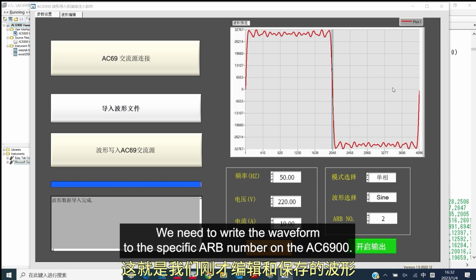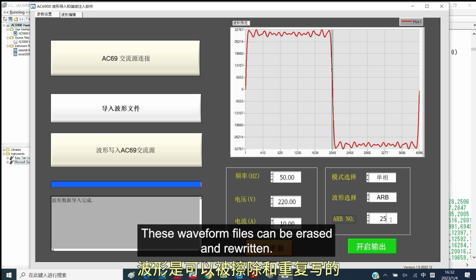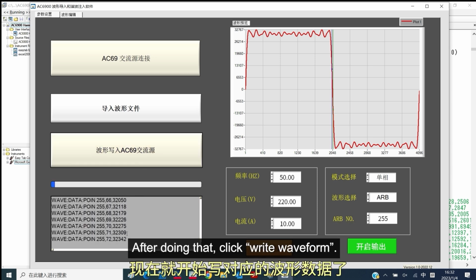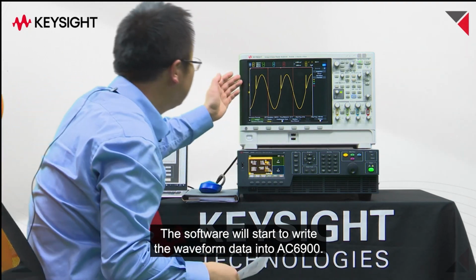We need to write the waveform to a specific ARB number on the AC6900. It has a total of 256 waveform files. These waveform files can be erased and rewritten. For example, we write it to 255. After doing that, click Write Waveform. The software will start to write the waveform data into the AC6900.